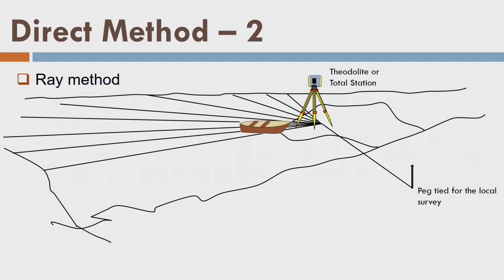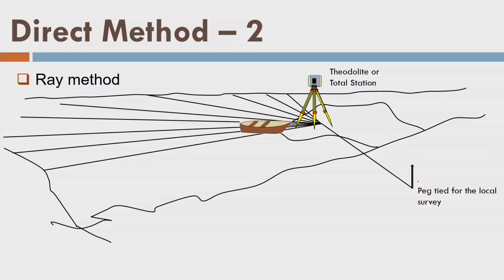Let us look into the ray method. In the parallel line method, I assume that there is a long shoreline and we are stretching one reference line between two reference marks. Now imagine that it is not possible to establish another reference mark, only one. Depending on the field situation, sometimes there is no place to establish the reference mark, or no way to refer it to our topographic survey. To connect the hydrographic survey with the topographic survey, I need some control stations which are well visible to me. Let us say only one station is possible to use, and this position is this one.